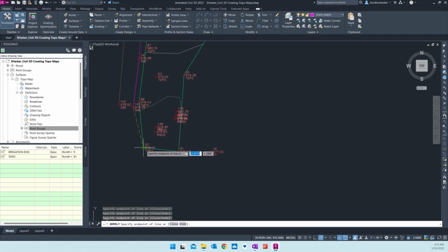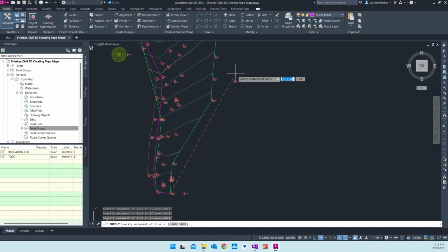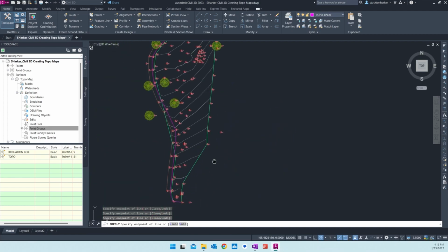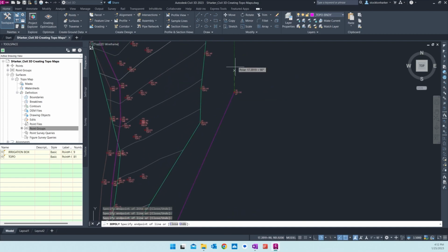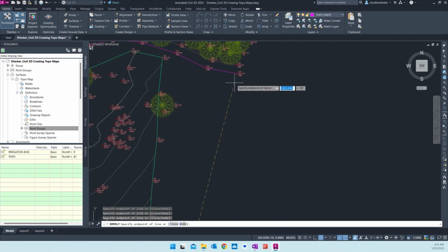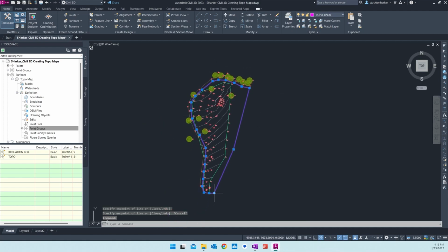And in this case, I'm just going to come to the edge of these topo points, and we'll come out to this light pole here, and then I want to connect back to the sidewalk edge here. Okay, fantastic. And I hit escape to end, and if I click on it and select this line that I drew, we can see that it is one complete closed loop.